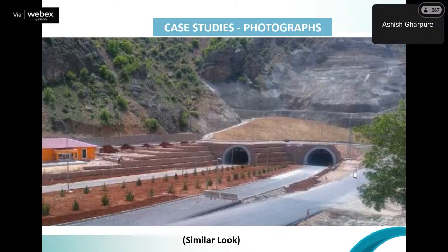Some of the outcomes of flattening the slope, and sometimes putting the portals, make an extra portal or false portal come out of the area, so that immediately next to the portal the landslide hazards are there. So if you come out and then cover them back, you will be safe. Next, please.